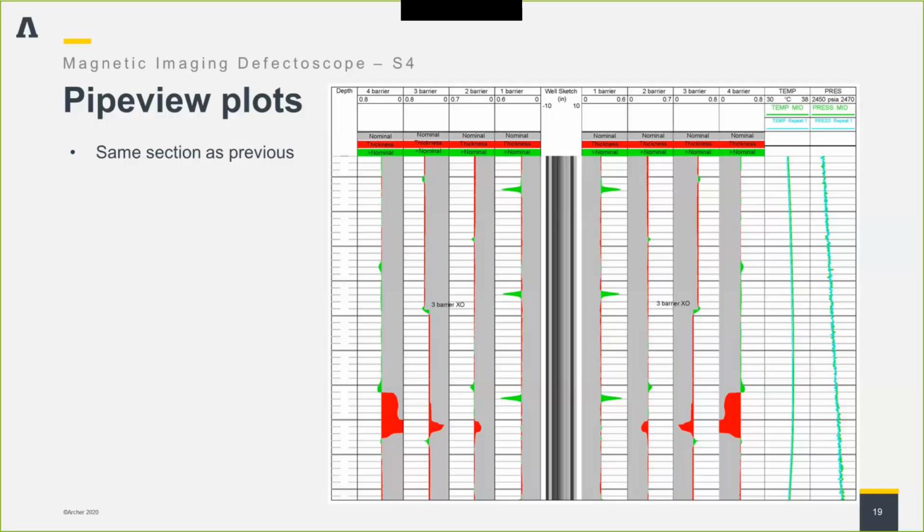Well, it's not the same as multi-finger caliper, because the multi-finger caliper is inspecting only the inside of the tubing or the first casing string, whatever the fingers are touching. So what you get is an interior profile. What you don't get is any indication of whether there may be external corrosion and the absolute thickness. So with a multi-finger caliper, you're assuming that the exterior is okay for any of your calculations on the remaining thickness. Intelligent pigging, I'm not entirely familiar with.